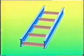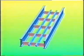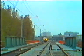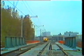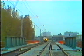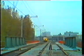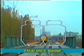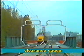Plate girder bridges comprise the main girders, the cross girders, the stringers, or, in case of a railway bridge, the rail bearers, and finally the deck. First, a railway bridge is considered. The following components and concepts characterize this type of bridge: the clearance gauge. Fixed objects are not allowed inside this profile.